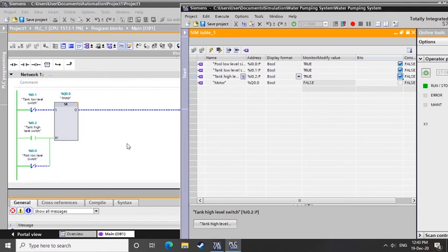Okay, so now as you can imagine, if you keep on consuming water from the tank, then the high level will slowly turn inactive. And then furthermore, more usage will turn the low level inactive too. And then as soon as it detects that, it won't send a signal, and the low level here will set, and then you will start pumping water into the tank again. So this will keep going on until the pool level is inactive.